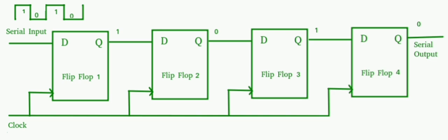Up or down counter. An up or down counter can count in any direction depending upon the control input. For determination of up or down counter: triggering with negative edge, clock connection Q acts as up counter. Triggering with negative edge, clock connection Q bar acts as down counter. Triggering with positive edge, clock connection Q acts as down counter. Triggering with positive edge, clock connection Q bar acts as up counter.